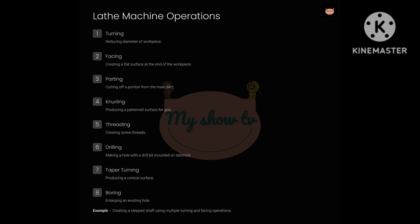5. Threading, used to make screw threads, such as on bolts or rods. 6. Drilling. Yes, you can also perform drilling using a drill mounted in the tailstock. 7. Taper turning, producing a gradually reducing diameter. 8. Boring, enlarging an already drilled hole. 9. Example, a stepped shaft made by turning and facing is a good real-world use case. Each of these operations is fundamental for component manufacturing in mechanical workshops.